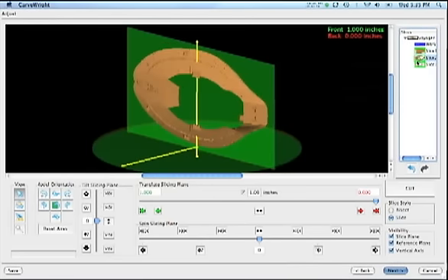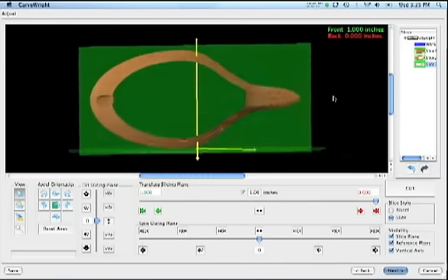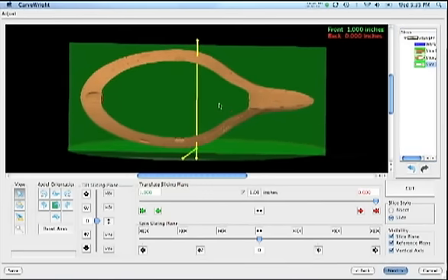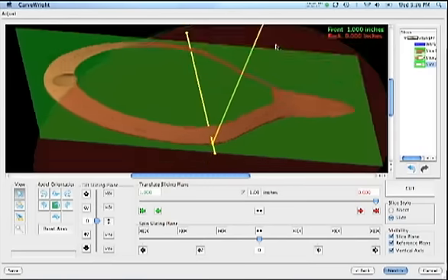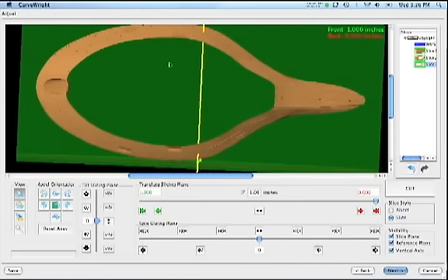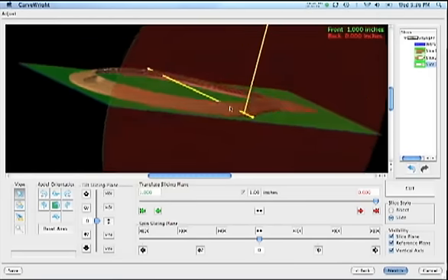So we've got 3 different slices now. Now, part of the problem that you encounter when you deal with those kind of inside out pieces, those little pink errors that we were looking at before, is that a lot of times you will not get the auto heal, the ability for the blank areas in between the model to automatically fill in, which our software does do if you've got a correct model. Now, I can correct things like this simply enough in our pattern editor, which we'll get to a little bit later.